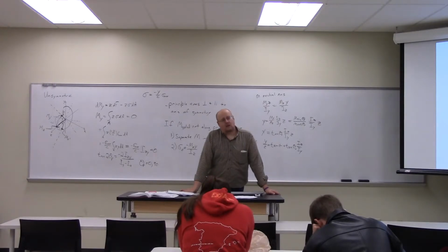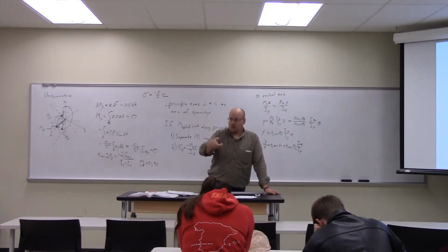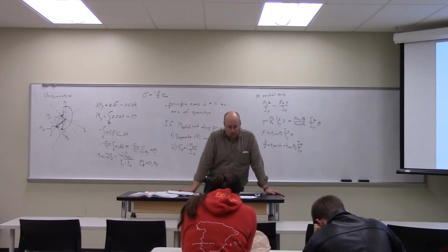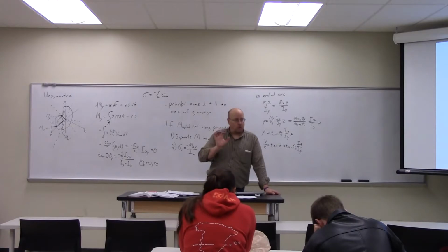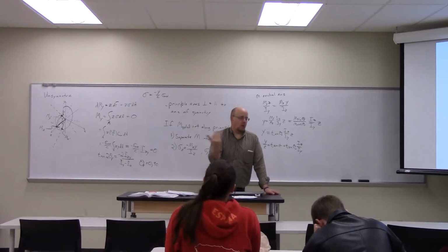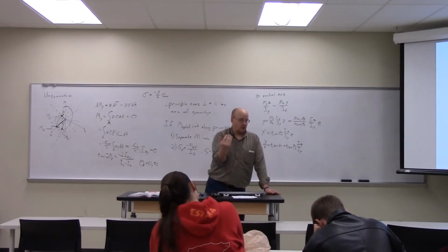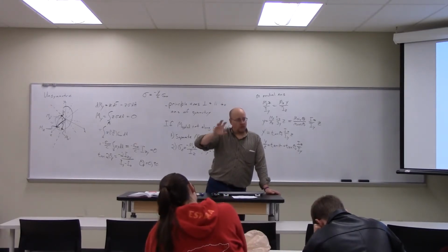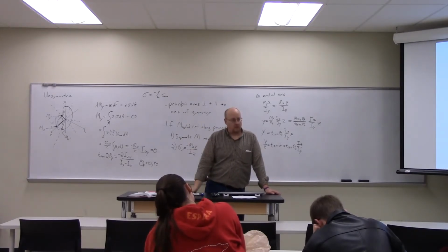And so then we would just go back and analyze that piece using the twist approach that we talked about before, the torsion. You get a twist out of the x component, you get bending out of the y and z components. Now, once we've completed this, we've covered all the possible deformations. A normal force along the length, shear forces, which can be applied in y or z, which we've already talked about. Torsion, which is a twist, or rotation, on the x, and then bending in the y and z. So we've covered all the possible bases.